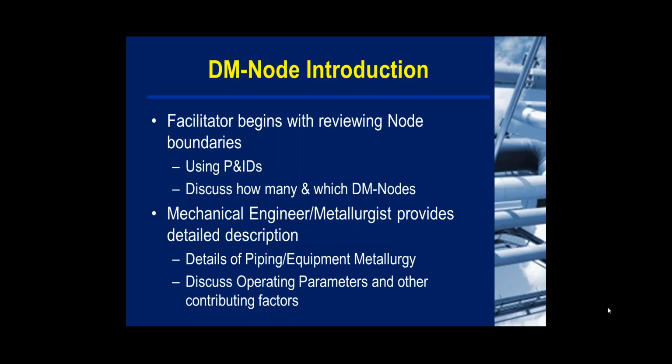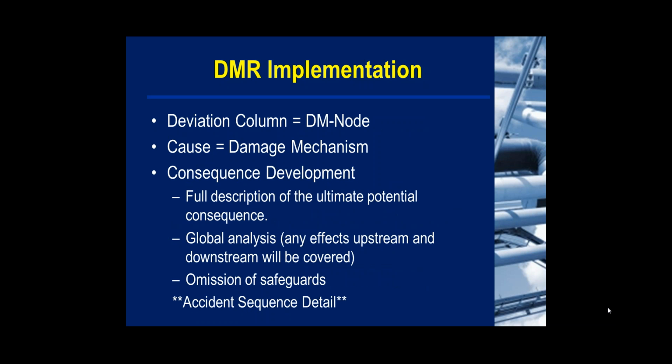Lastly, for your preparation section here, if a corrosion study has already been completed, which we know a lot of refineries are doing, the preparation step becomes a lot easier, and your damage mechanism review becomes fuller because you're able to use corrosion loops, and CCDs provide a lot of good information to fuel discussion, as well as site-specific data like wall thickness and integrity operating windows, or IOWs.